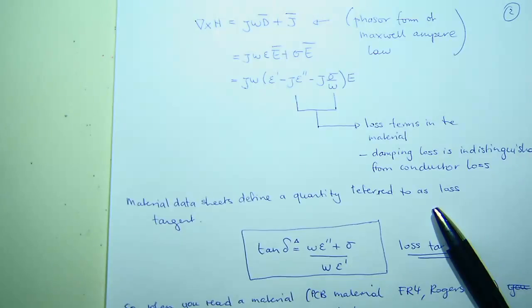And essentially what that does is it allows you to work out the ratio of the signal that is actually propagating versus what you're actually losing, right? So therefore it provides you with the information so that you can know what your loss is per millimeter of track length, right? Because when you're making tracks on a PCB board, if they're short, you don't really care because the loss isn't quite large.